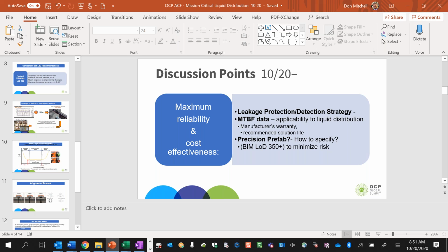So, Don, this is John Musilli, a former Intel engineer. Hey, John, how are you doing? So we had to deal with water inside our data centers, and we had some very high volumes of water. We were running upwards of 16,000 GPM through some of our rooms overhead for some close-coupled cooling solutions. We wrestled with this, and we discovered two things. One, it's the small leak that was the bigger concern, because a small leak leads to a bigger or more catastrophic event. But the most likely event was a drip or a spray event.